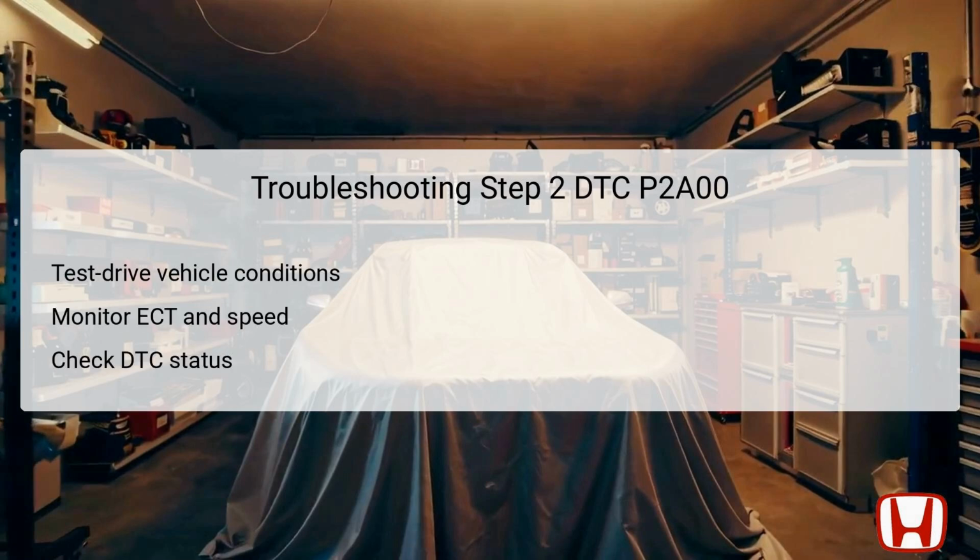Following the initial engine warm-up, the next crucial step involves a test drive of the vehicle under specific operating conditions. It is essential to monitor the engine coolant temperature, ECT Sensor 1 reading, ensuring that it exceeds 158 degrees Fahrenheit, 70 degrees Celsius. This temperature indicates that the engine is working within a valid range for emissions testing.